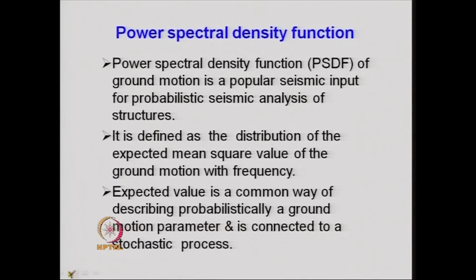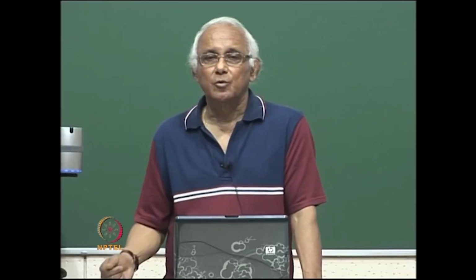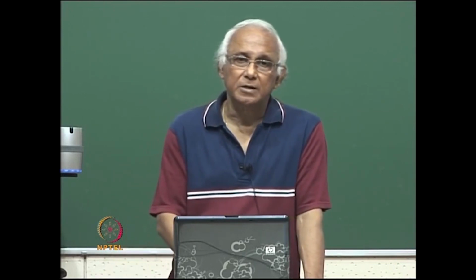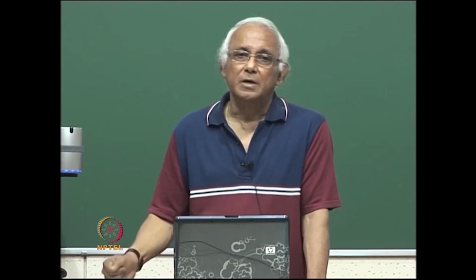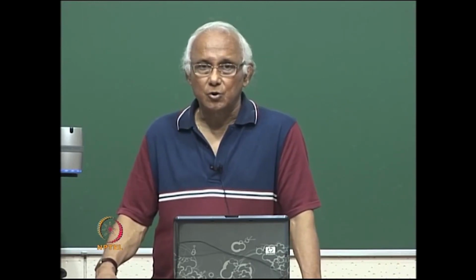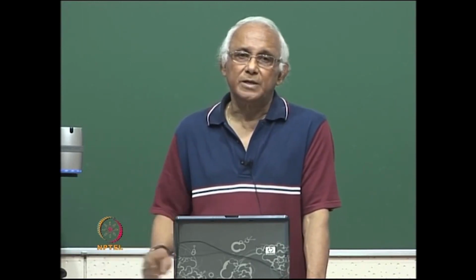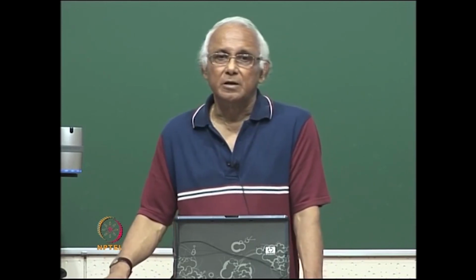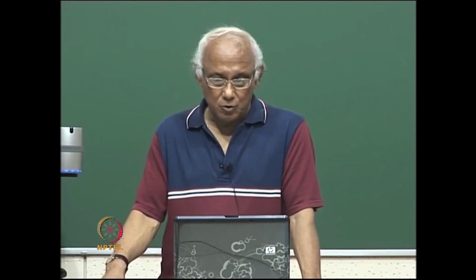The power spectral density function again is a form of input which is given with respect to different frequencies, or we can say that at different frequencies we have different power spectral density function ordinates, showing the frequency content of the ground motion.